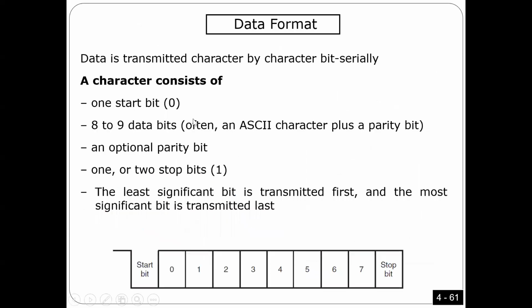Anyway, now the data you are going to send, the data format. The data format should have this format, guys. We have a bit in the beginning. This bit we call a start bit. So any data you have to send, you have to put it in a frame. Also, this is something related to communication. The frame here looks like something like that. The frame is, you have a start bit.